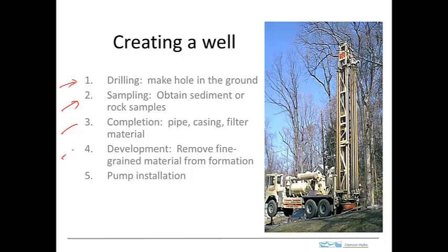The development process involves removing the fine grain material or some vestiges of the drilling process that are in the vicinity of the well, unclogging clogged pores, and allowing water to flow more readily to the well. And then in some cases we might install a pump.